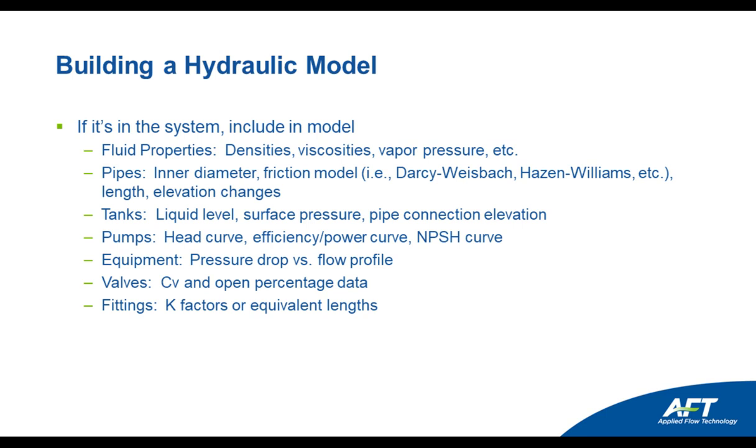As far as modeling your pumps, it's good to be able to specify your pump head curve and flow, or specify an efficiency or power curve. That way, the analysis tool would be able to calculate how efficiently your pump is actually operating. And then including the NPSH curve is also really important, because you don't want to have cavitation inside your pumps, and you want to ensure that you have plenty of margin between the NPSH available from your system and the NPSH required for your pumps.